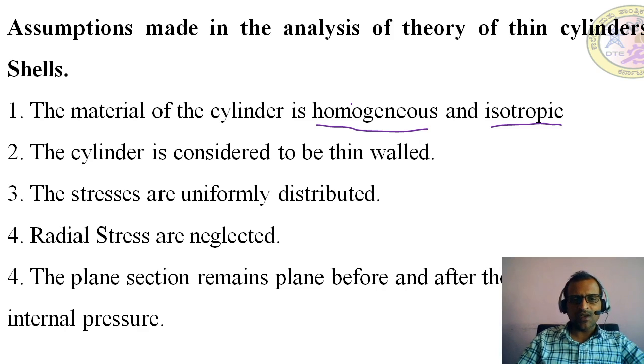The third one is that the stresses are uniformly distributed. Whatever liquid or gas you are going to store inside the cylindrical shell under pressure, that pressure puts a force on the walls of the container. Because of that force, some stresses are induced in the cylindrical shell. Those stresses are assumed to be uniformly distributed. This is one more assumption, but practically it may not be correct. For our further calculations, we need to assume that the stresses are uniformly distributed.